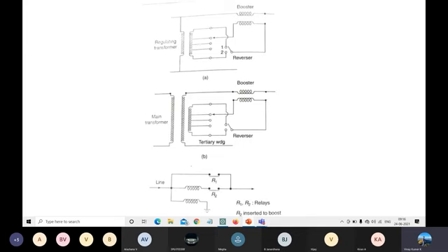And also, one more thing is that the buck transformer or boost transformer is an economical solution to adjust the line voltages. We use these transformers to adjust the line voltages slightly, not very much. Only if you want to use booster transformers or tap transformers at very sensitive equipment. So we need to concentrate on the sensitive voltage signals as well. At that time we need to inject or balance the line voltages slightly above or below the nominal value of our voltage levels. Okay.